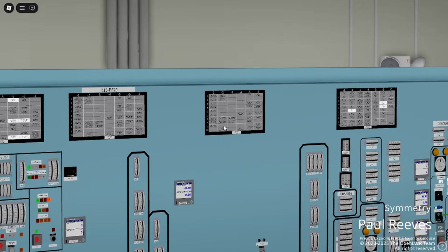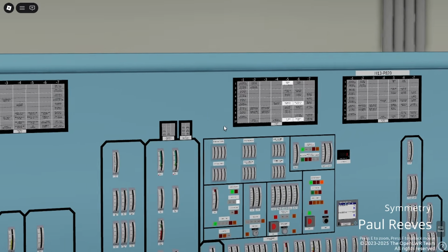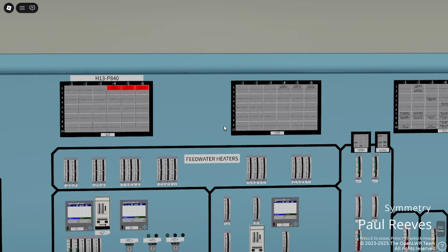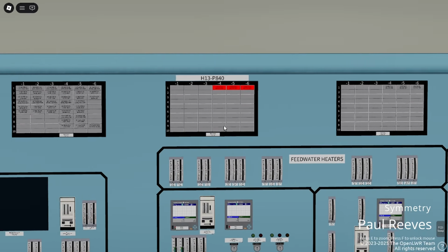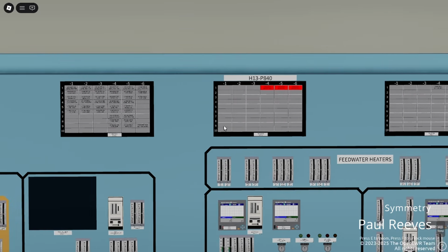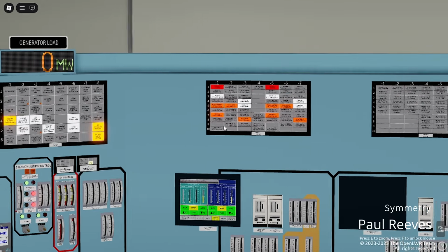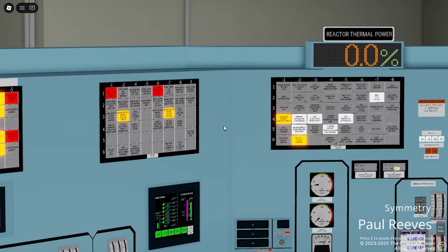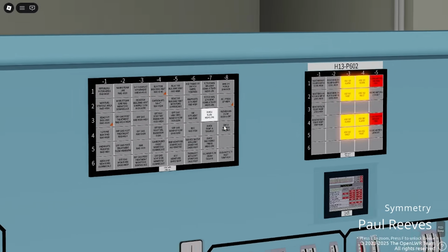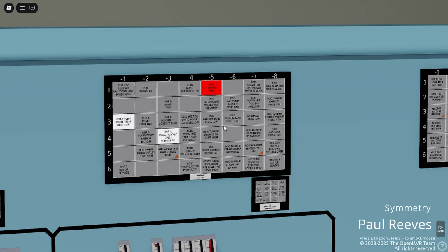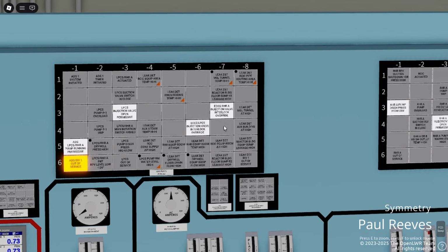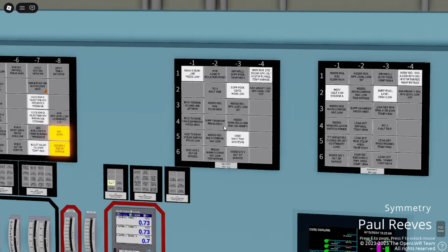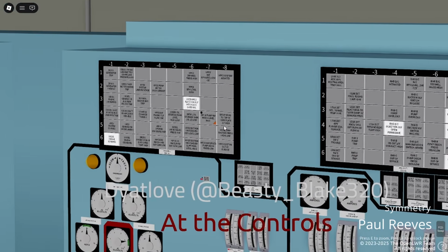Operators are getting high drywell pressure annunciators. This is caused by the safety relief valve's tailpipes breaking. The safety relief valve pipe broke during the earthquake. High drywell pressures and temperatures can cause failures of monitors and equipment in the drywell. That's why we have high drywell pressure actuations that automatically isolate the drywell to prevent steam leaking. Operators will try to vent the steam through the standby gas treatment since they have determined there is no significant radiation.